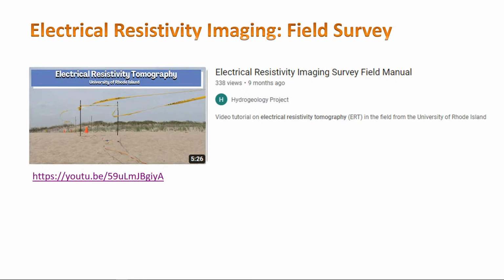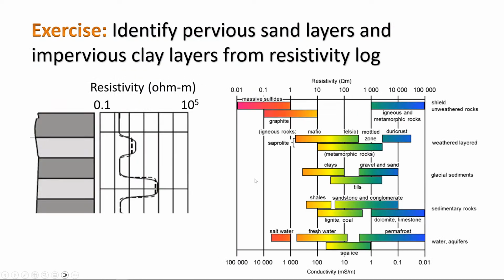We're going to get a hydraulic conductivity value, not from a permeameter but from a pumping test, and we will overlay them with electrical resistivity value measurements. We will do this to characterize the subsurface, to create the hydraulic conductivity field, and have a rough understanding of different hydraulic conductivity values for different zones in our field.